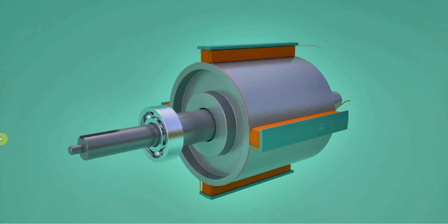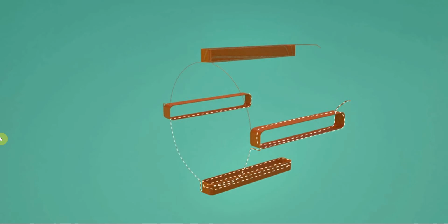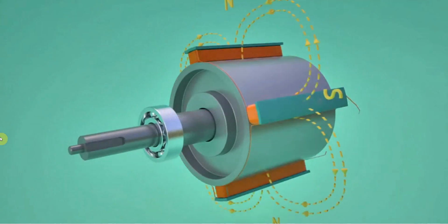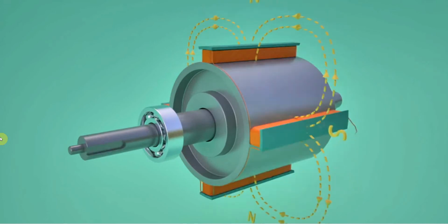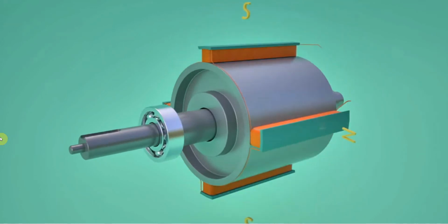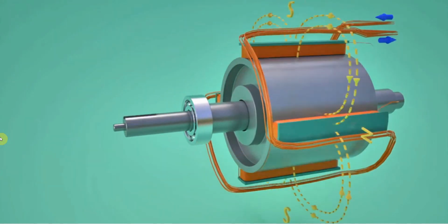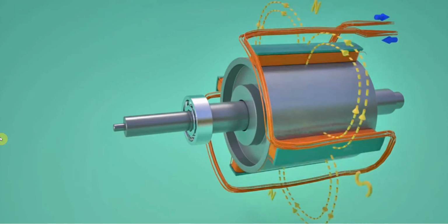The kind of rotor shown here is known as a salient pole rotor. For gaining better insight into its working, let's consider a rotor with just 4 poles. Rotor coils are excited with a DC power source. The rotor is made to rotate by a prime mover. This makes the rotor flux also rotate along with it, at the same speed. Such revolving magnetic flux now intersects the armature coils, which are fitted around the rotor. This will generate an alternating electromotive force across the winding.